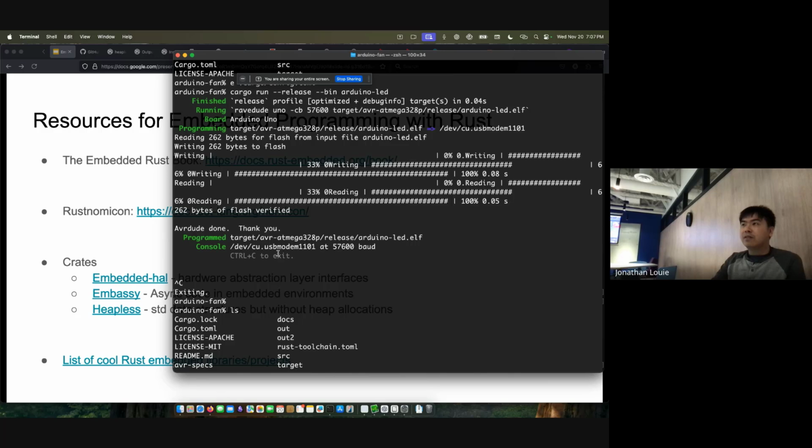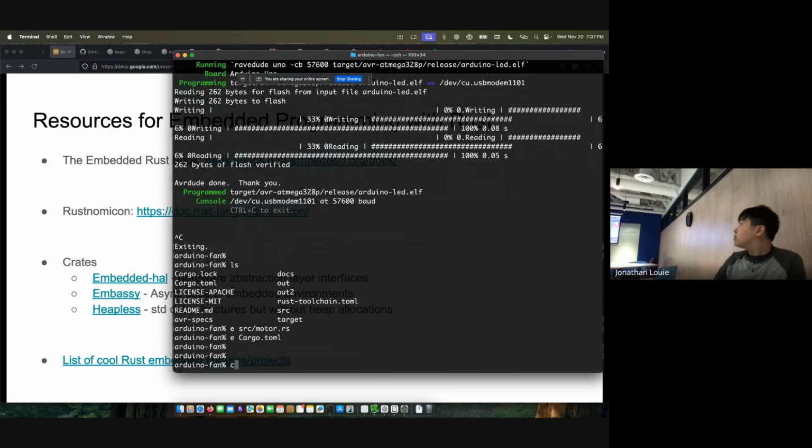So I don't know exactly what semi-hosting is, but in environments where, let's say you're lucky and you do have enough memory that you can run multiple programs on whatever your embedded device is. So let's say it's an ARM device and you've got megabytes of memory available, which doesn't sound that big, but that can be a luxury. You can actually launch things like GDB on the device, and then you can do remote attach and you can set the breakpoint on source code level. Yeah. Okay. Actually, you can even try that out on these.